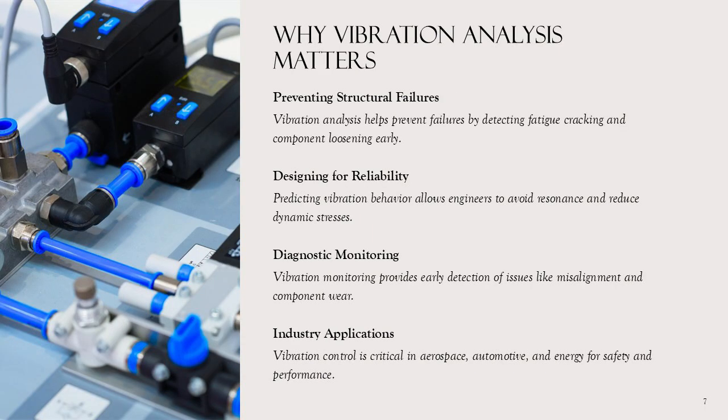Vibration analysis is essential in engineering because it helps prevent structural failures, reduce maintenance costs, and ensure operational safety. Uncontrolled vibration can lead to fatigue cracking, fretting, and loosening of components, which compromise system integrity. By predicting vibration behavior, engineers can design systems that avoid resonance and excessive dynamic stresses. This proactive approach enhances reliability and extends equipment life.